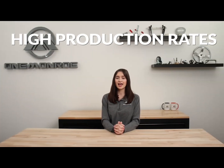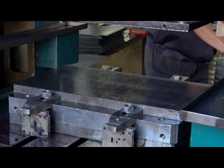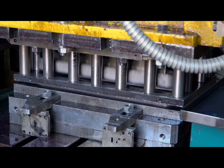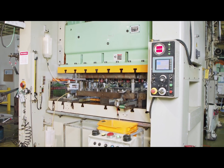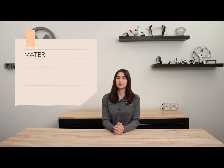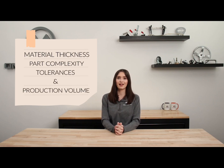Some of the advantages of metal stamping are the high production rates, accuracy, and cost effectiveness for large volume manufacturing. Additionally, it can be easily automated for increased efficiency. Tooling and die design are critical aspects of metal stamping. The dies are custom made to match the desired part's shape and specifications. The design process handles material thickness, part complexity, tolerances, and production volume.